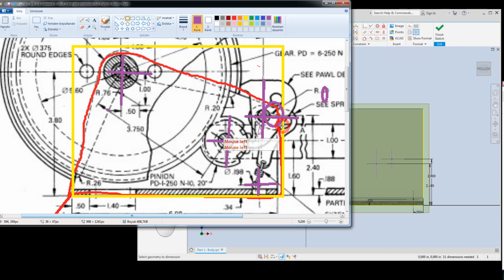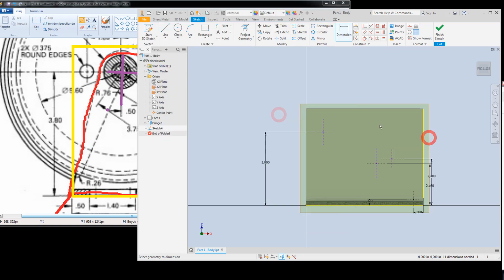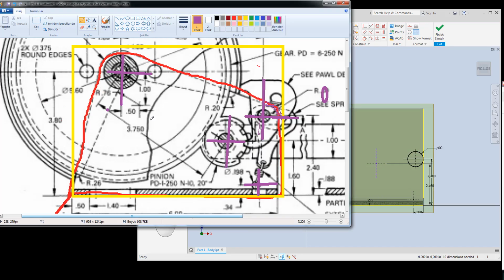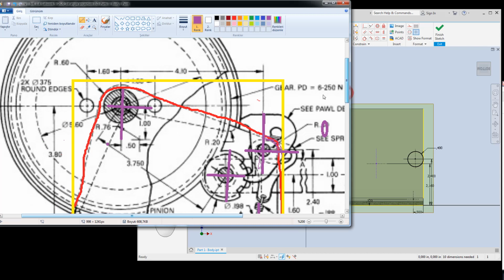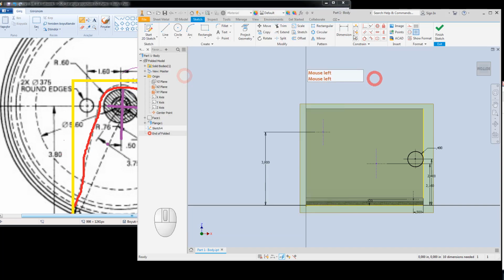I have a radius relationship like this. I have a radius relationship at this point, which is I'm going to use this one, having the radius here 0.4, and I will make this dimension stick to this edge, and I will also give the dimension relationship, which is this one. It is 4.01 millimeter far from this line.